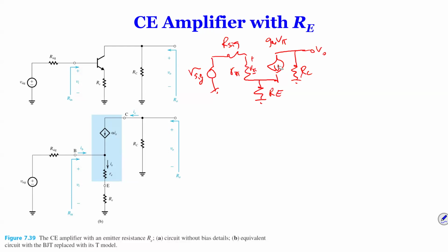Again, as I said, it really is saying that, yes, you can do it, but it becomes more difficult because you've got a node at the emitter with 3 connections. So that's what makes it more difficult. By doing this T model, it makes it a little bit easier. Again, you guys remember when we did the T model, there's RE at the bottom, that's current up there.